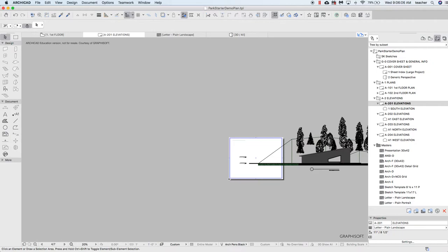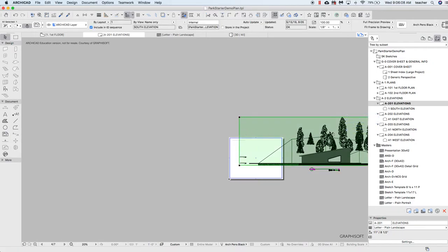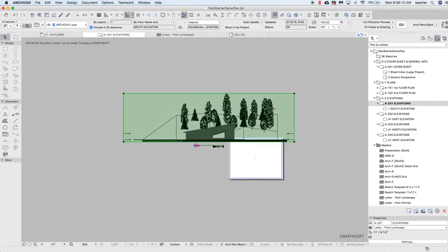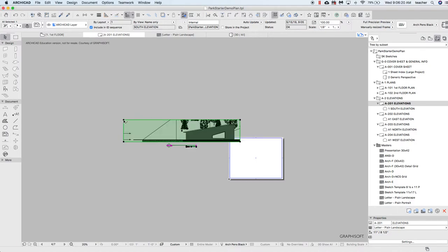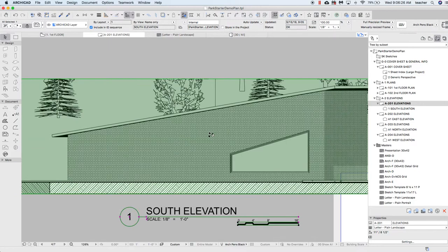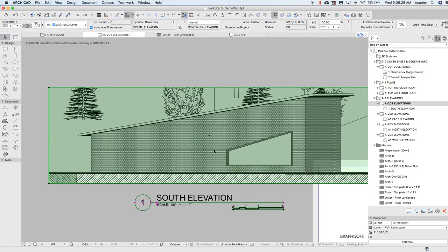And then what you want to do is trim your image down. So I'm going to move it first. And we can see I've got a lot more information than I need. I will bring the frame down just to focus on the building or whatever it is you're trying to show. And we can see that I'm not parallel to the building in this elevation because I see both the south wall and the east wall. If I were to rotate my camera angle, this would also auto update.